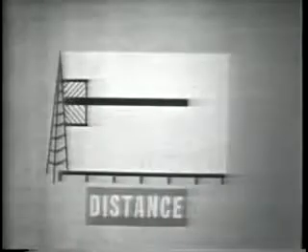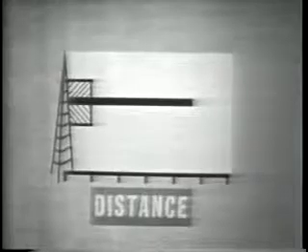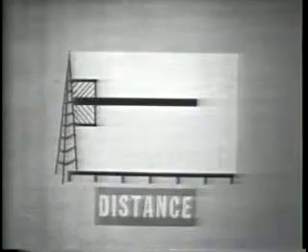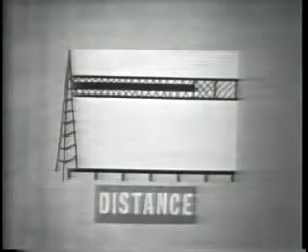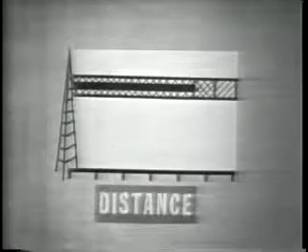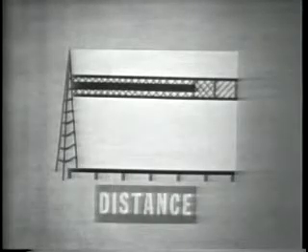Now you recall that in conventional AM at 100% modulation, one sideband contains only 1/6 of the total transmitted power. Thus, if all the power were placed in one sideband, its level would be increased 6 times. This increases the power in this sideband by a factor of 6, but it only increases the intelligence power by 3, since part of the power was already intelligence power in the sideband that was removed.